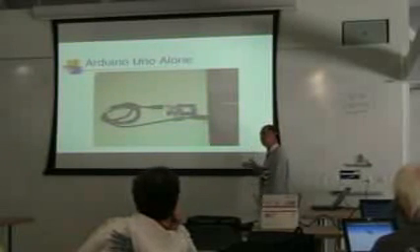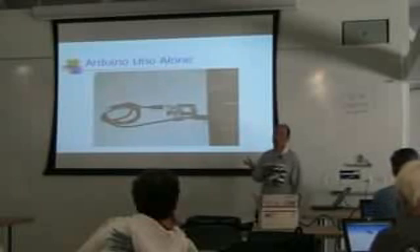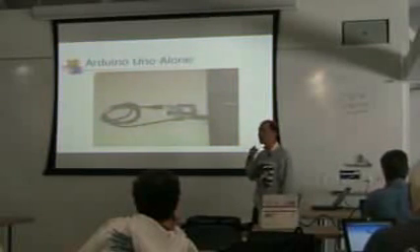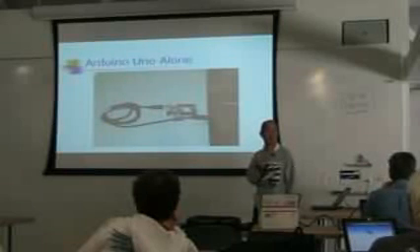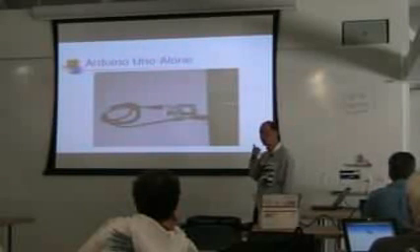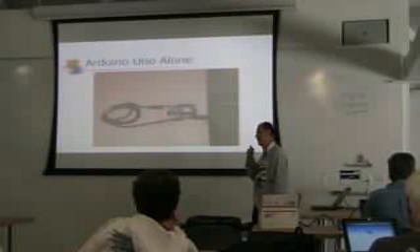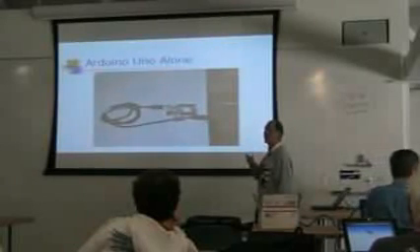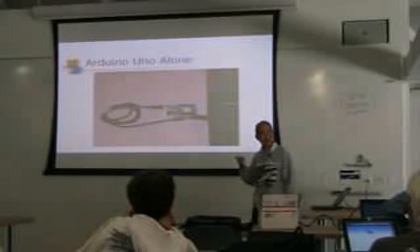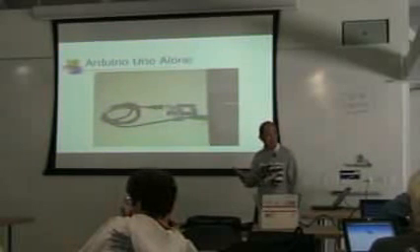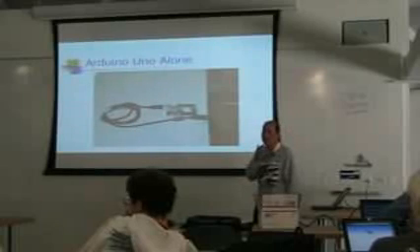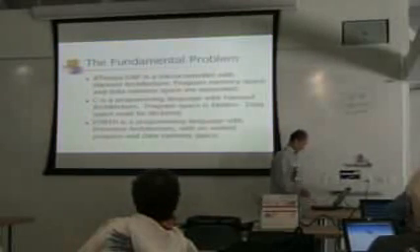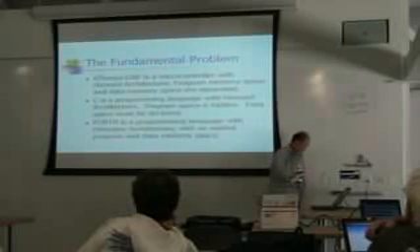You cannot put the real code in RAM because the ATmega328 does not execute anything out of RAM. If you want to execute any real code, it has to be in the flash. But we can always build a virtual Forth machine. And with a virtual Forth machine, well, you can do anything, right? So that's the idea.